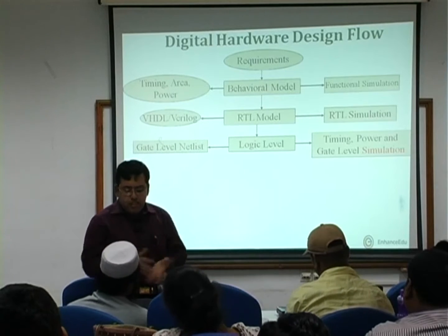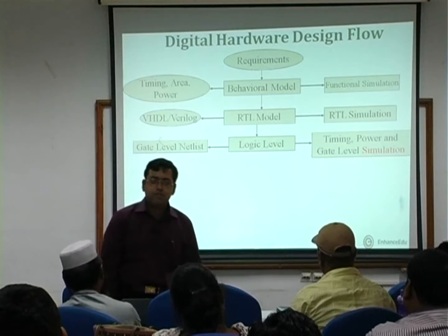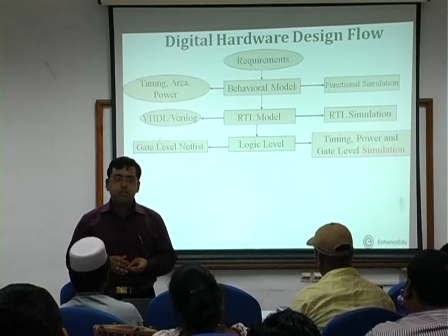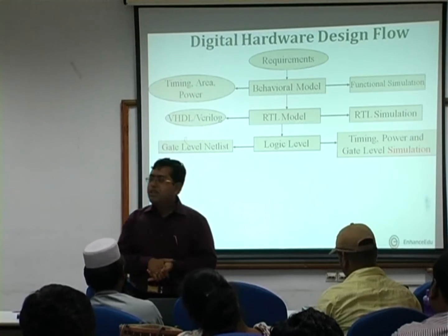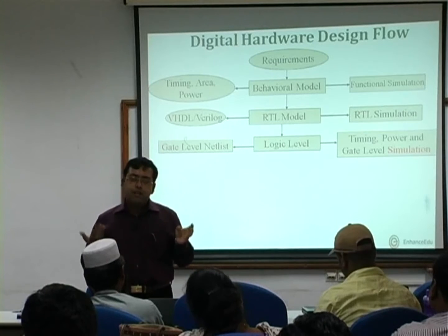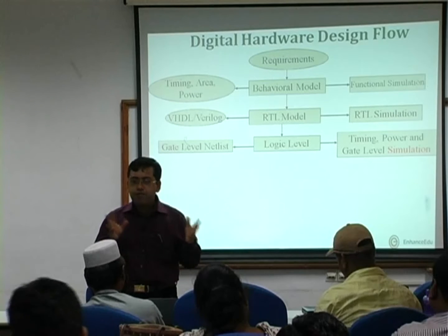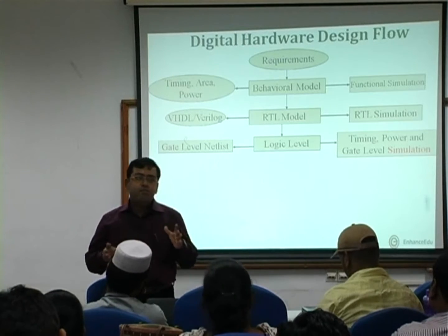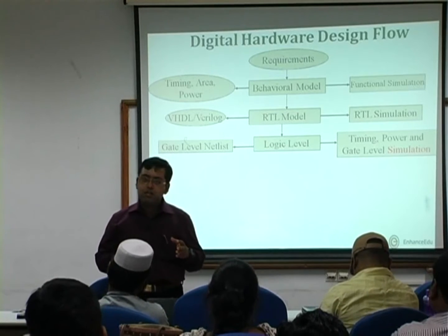And for doing this gate level simulation, of course you need to generate the gate level netlist. Do you have any idea of a netlist? A netlist is basically a specification of interconnection of components in a circuit in a formal way. There are two ways by which we can express the interconnection of components in a circuit.